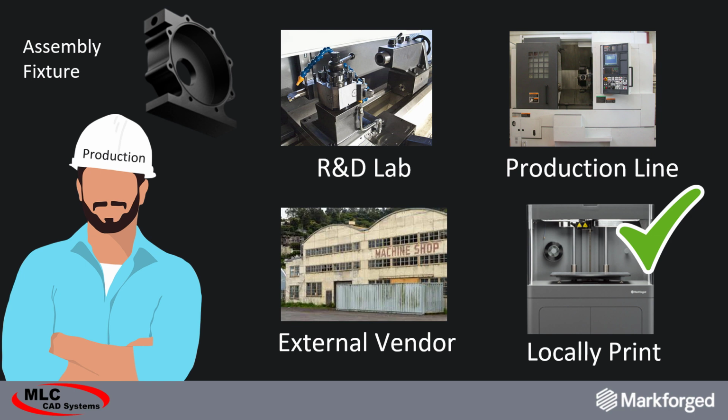By 3D printing your fixtures, your jigs, your tools, whatever, you're going to be able to quickly replace those. And if it's a one-off job, you can confidently throw it away without thinking that you're throwing away some masterful piece of artwork. Also saves a lot on storage. The fixtures end up being a lot less heavy, but still very strong and stiff. And so there's a lot of benefits. Once you go digital with a lot of your manufacturing, you can really start to see a lot of benefits in your fixturing and your assembly processes by using additive manufacturing technology.